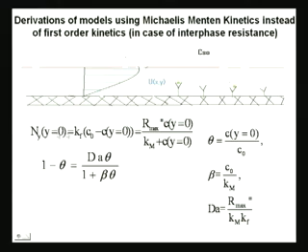What have I done? Only this part of the equation is the one that I make dimensionless. So, k f times C naught minus C equals R max C over k m plus C. If you take k f to the right hand side, you get R max over k f, and remember R max over k f is on this side here, so this side gives you 1. So, divide both sides of the equation by C naught. This will give you 1 minus theta.